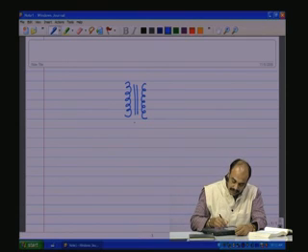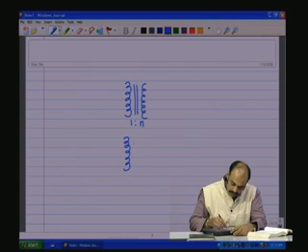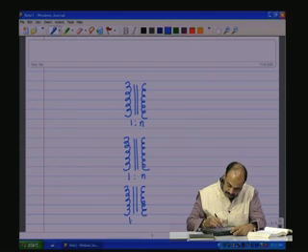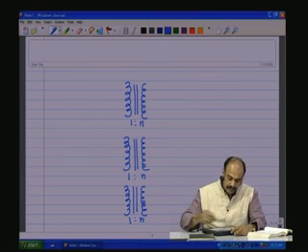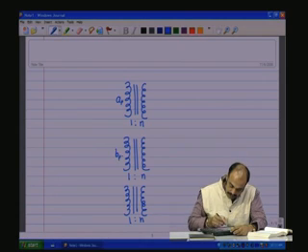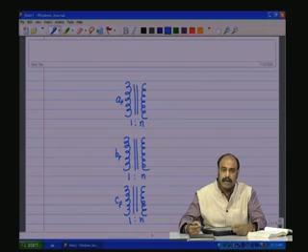So, you have the primary and the secondary, and we will say that is 1:n. We have another single phase transformer with primary and secondary, which is also having 1:n, and one more single phase transformer with primary and secondary with turns ratio 1:n. These are three single phase transformers. Now, it has three primaries. We will call them A P, B P, C P. Three primary windings, A P, B P, C P.